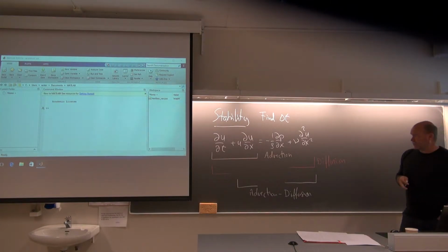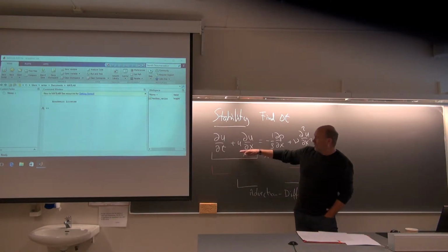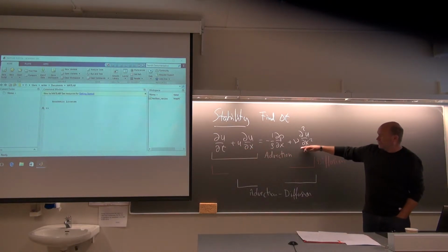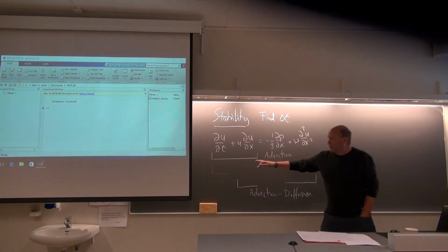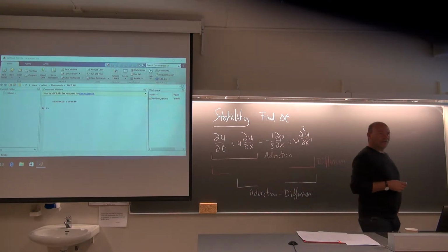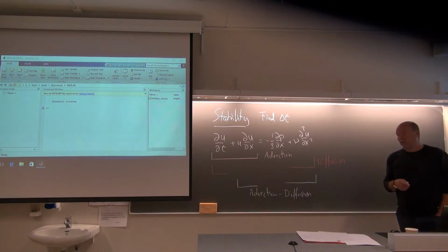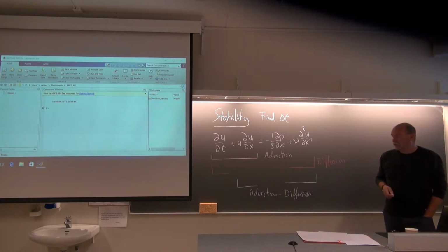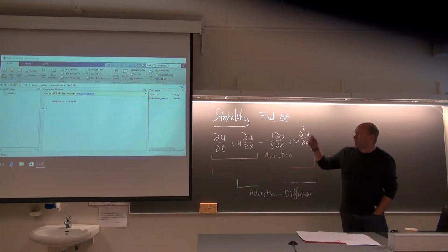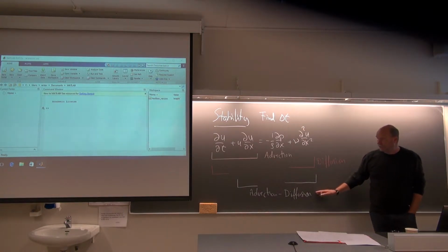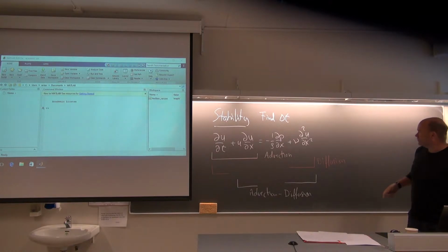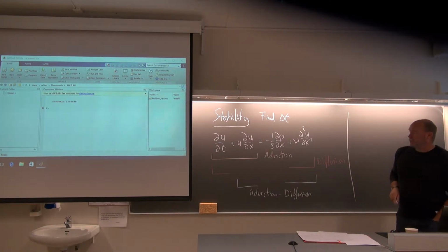If you look at the last choice, only the advection acceleration term and the diffusion term, I have skipped the time derivative altogether, so delta t shouldn't enter into the problem. Still, it will give us some requirements, not necessarily for the time step directly, but a requirement for the delta x, how small your delta x has to be. So this is the plan.